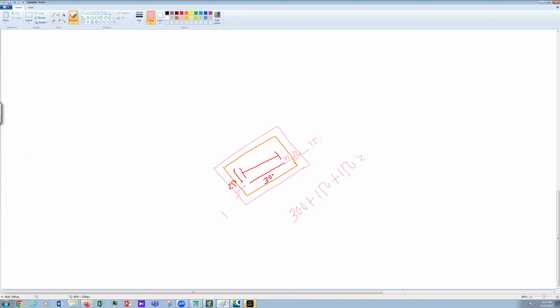If you have any brick wall or masonry wall going through your RCC column, then you will also have to add the width of this brick or masonry work. For the time being, we just consider 600 as the length.